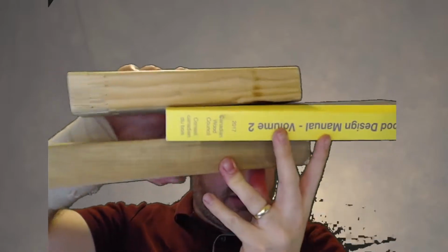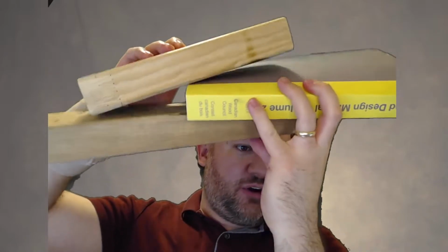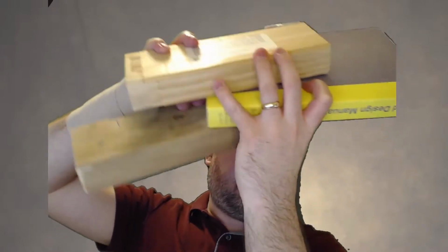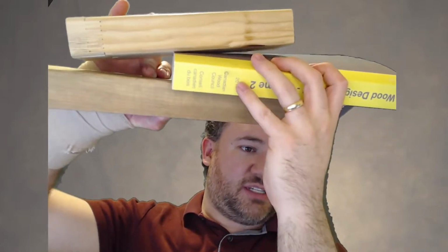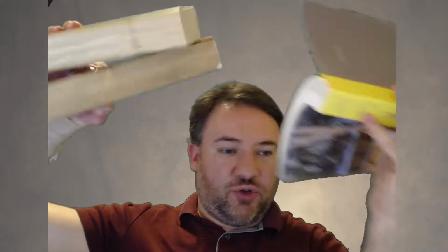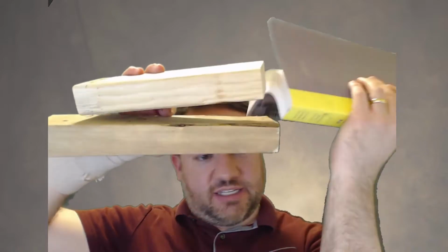Now, if I have three members, which I don't really have three pieces of wood here, but let's say that my book is one piece of wood or a piece of steel or something, and I have two pieces of wood on the outside. Okay, so here's my design manual. So now if I were to pull this connection apart like this, and I've connected all three of these pieces together and I pull them apart like this, I'm going to have two members on this side of the connection. So these two together are taking that tension load on this side, and the book in the middle is taking all of that load by itself on the other side. Okay, so this side of the connection then has two members, and this side of the connection has one.